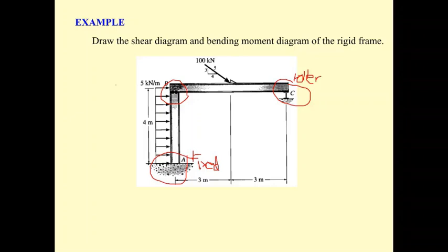When the joint is like this, we separate the beam, which helps us analyze the structure. The fixed support has 3 unknowns, and the roller support has 1 unknown. That means we have 4 unknowns, which is larger than the number of equilibrium equations. If we consider the whole structure, we cannot solve for the 4 reactions.